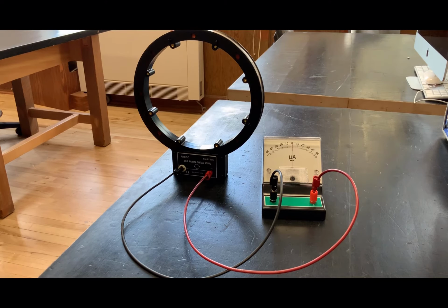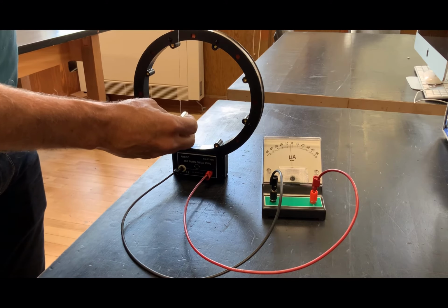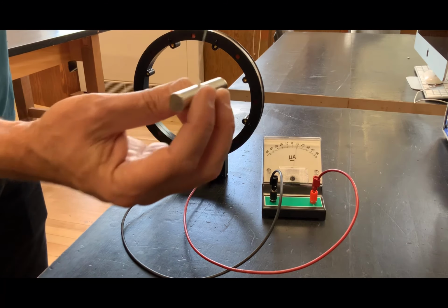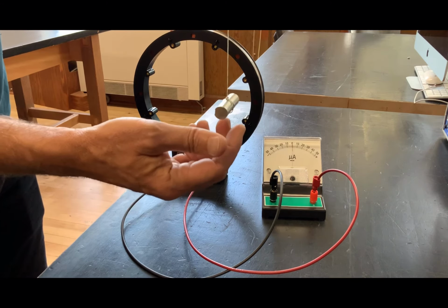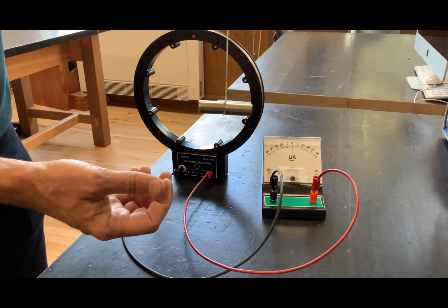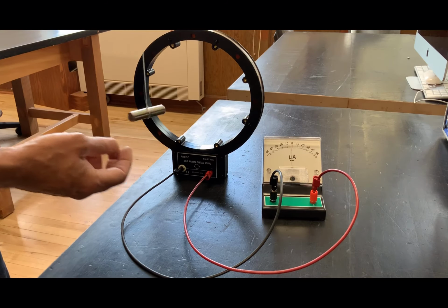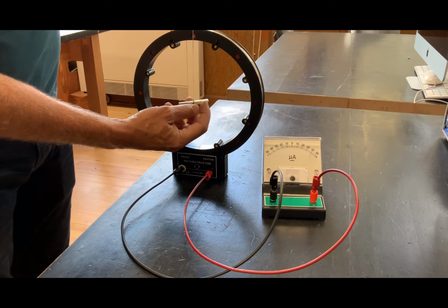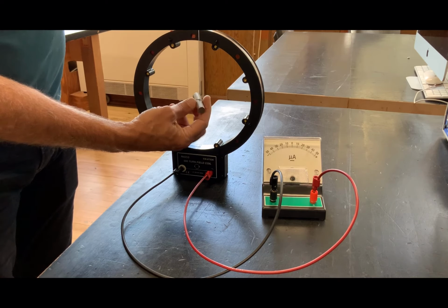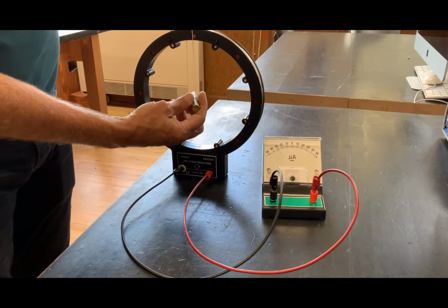We could also change the magnetic field direction. So what I've done is I've taken a permanent magnet here and put two of them and clamped them onto a string. Okay, it actually really wanted to line up with the field of the Earth. So this is a compass. But I can also put that in here and see what happens. So as I turn this, you can see we also get a current. So the field strength isn't changing so much, it's just changing the direction.